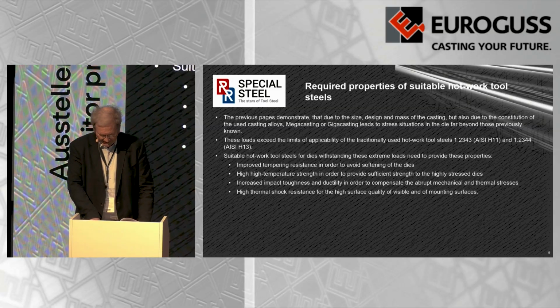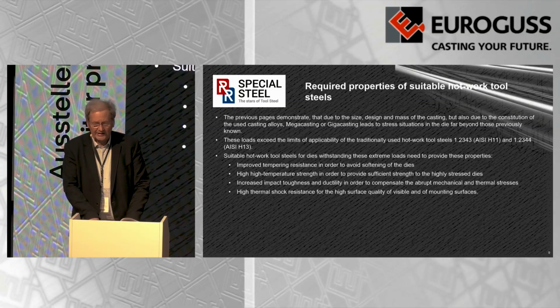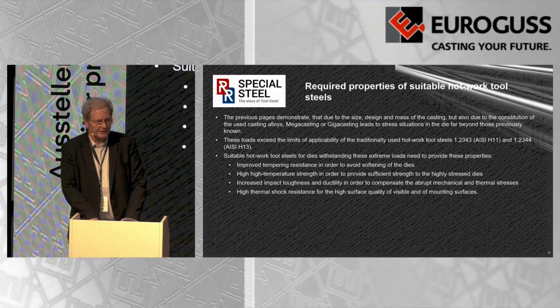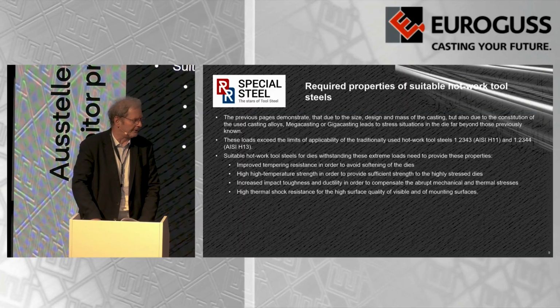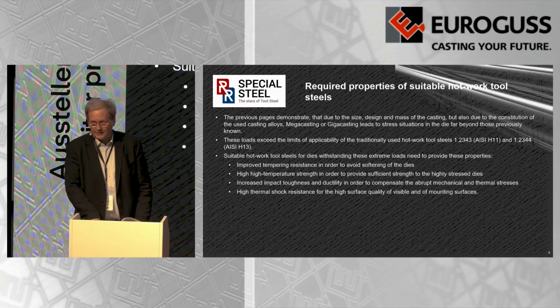Stresses in the die can easily exceed the limits of applicability of the traditionally used hot work tool steels like 1.2343 or 1.2344, H11 or H13.